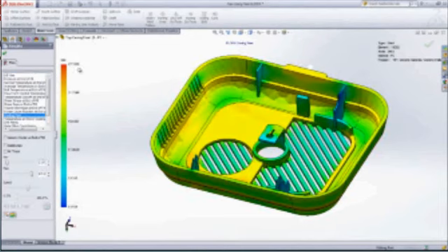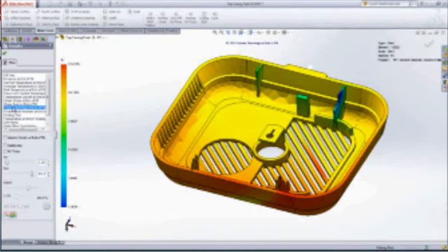It's because the wall thickness usually drives the cooling time. Cooling time is often about 70% of the overall injection molding cycle time. This means that by improving the geometry of your model, you can reduce the cycle time and also lower the price of the part.